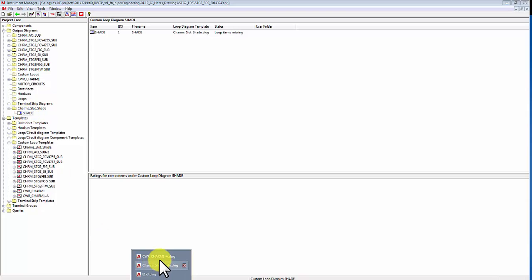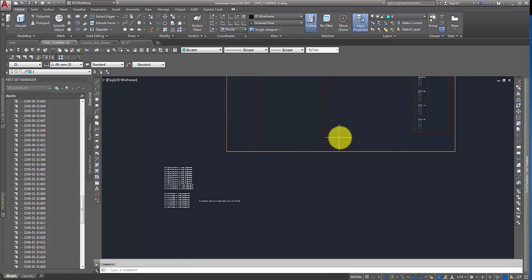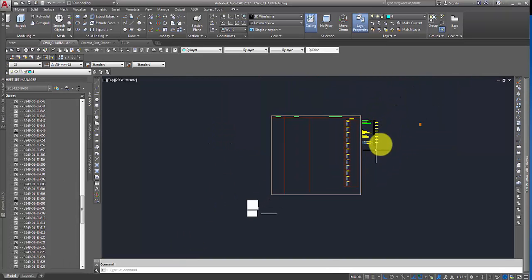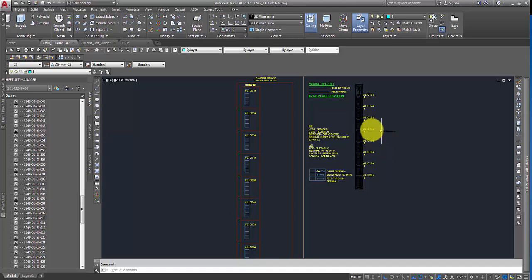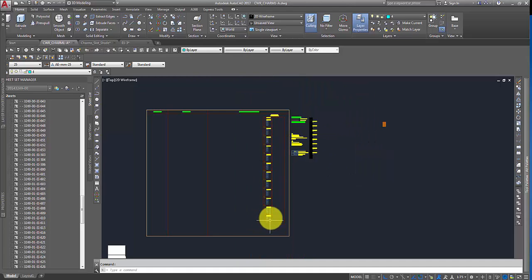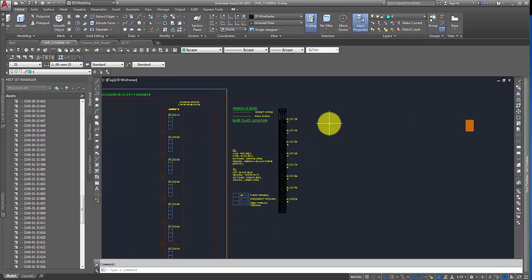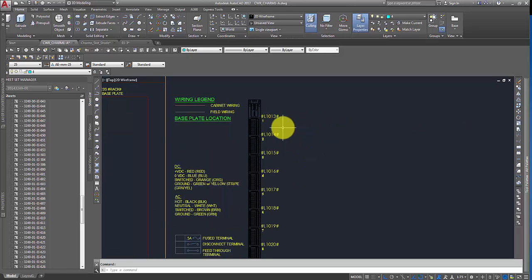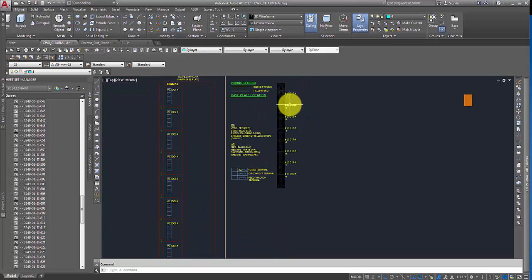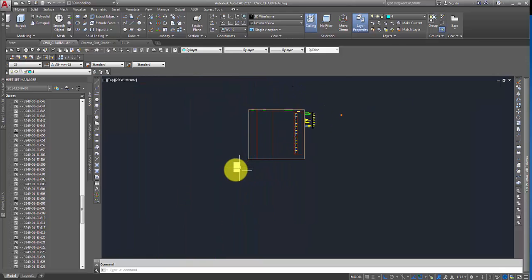So if we look at the actual template of the card that it goes on, here's the template itself. We know we've got 12 loop diagrams for our individual elements, individual CHARMs that are going in. So here we have our 8. Oh, by the way, this one over here is just in case people wanted to do a manual insertion after the fact. It just gives them options. But what we have is the automatic. So let's have a look at the hints.